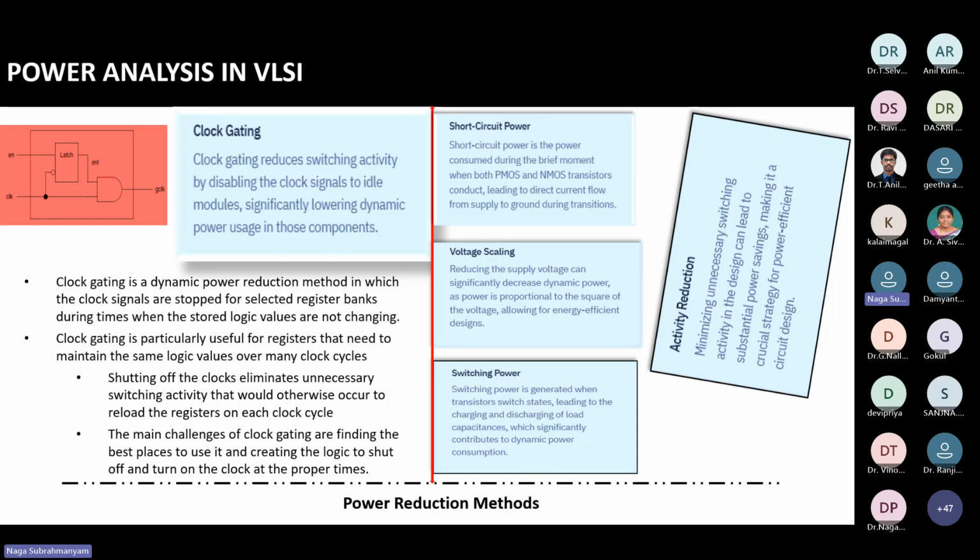As soon as the system starts to wake up, as soon as the PLL starts working, as soon as the crystal oscillator oscillates, it produces the signal to the PLL. Now the PLL wakes up, then the system comes into the wake up situation. Once it has started, you never see the clock die. This is the fundamental rule of digital design.